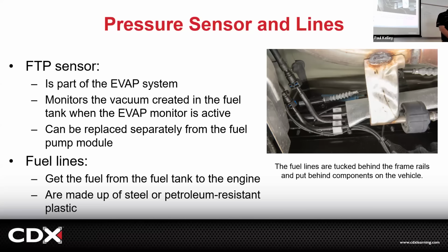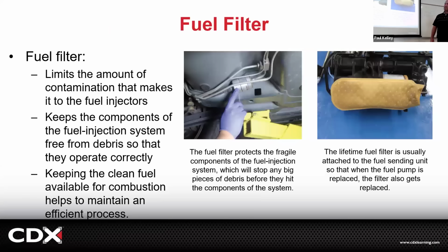Safer, more better. Cool. And then of course we got fuel filters that can look like this. This was old school. We used to do these fuel filters all the time. Ron knows about these fuel filters. You'd be cracking that fuel filter loose and you'd be working on it like this. By the time you crack it loose and the fuel's still in the lines, all the fuel's going to go down your line, down your wrench, down your arm, and you're going to feel it when it gets in this area. You'd be like, ow, I'm burning.